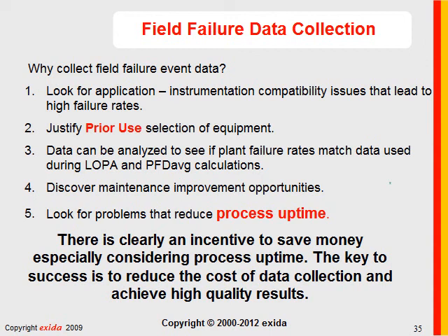So, we ask ourselves, why collect field failure event data? We are looking for application and instrumentation compatibility issues which cause excessively high failure rates, typically due to a site-specific installation error. We might be gathering field failure data to justify the prior use selection of equipment, especially if we don't purchase certified equipment.